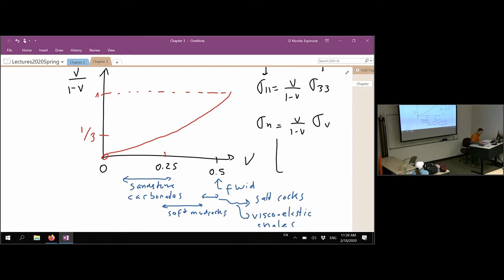And here you know that effective vertical stress is just the total vertical stress minus pore pressure. And if you want to get what is the total horizontal stress, you just need to add to the effective vertical stress the pore pressure. Okay? There is a P there. I cannot get there. The stylus is not getting me to get in there. But it's just the effective vertical stress plus pore pressure.